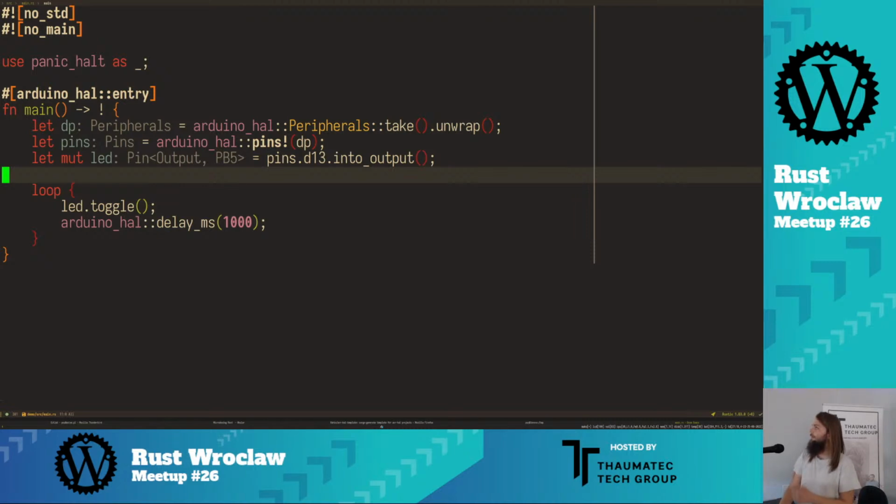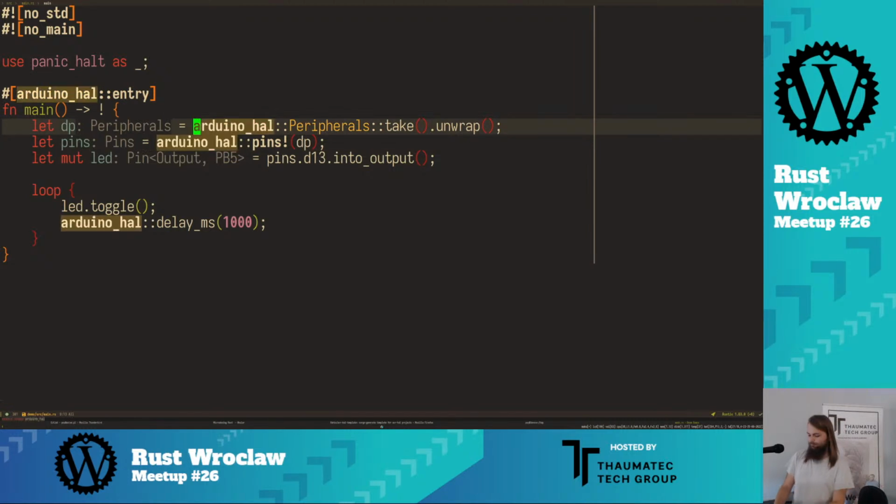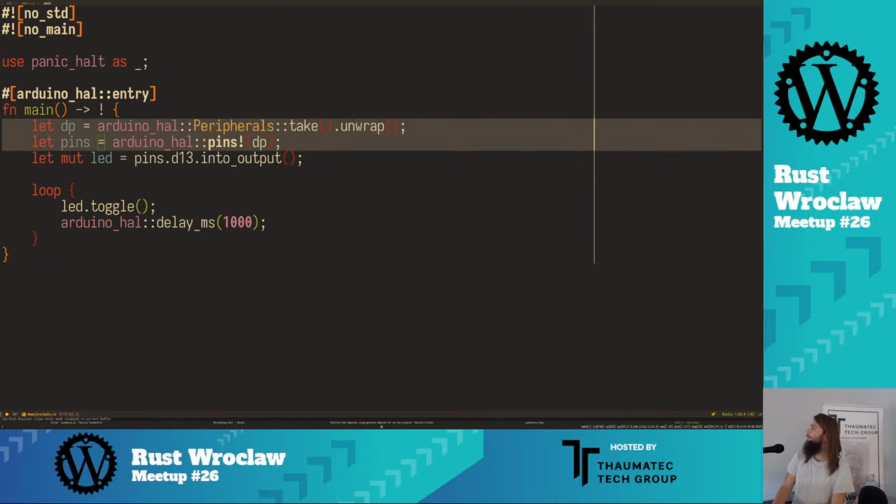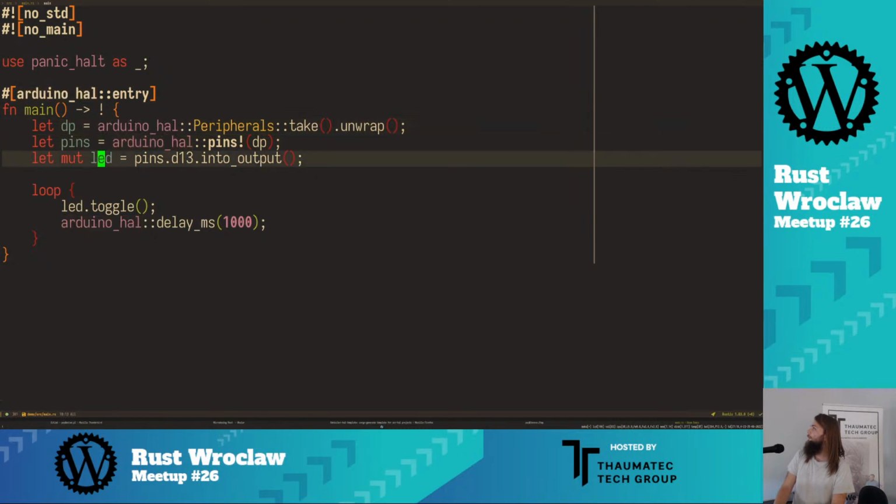And in this case, what the program does is, this is some initialization stuff. It prepares the CPU. Then we'll see that it takes some pin, marks it as output pin, because a pin can be input when it's supposed to accept some information from the outside, or output when it's supposed to go high and low as you wish.